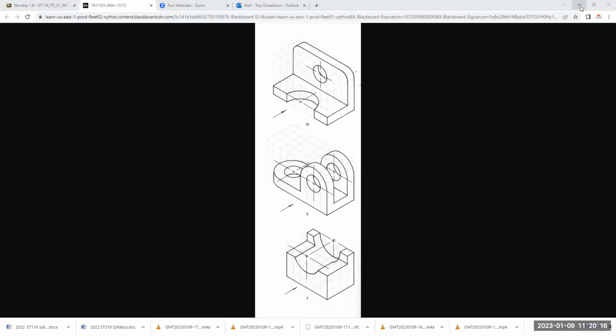I don't do that because this is small. I like big, like lots of space, right? So here's where I draw. But in paper space, this is where the title block should go, general notes, anything like that, not dimensions. Dimensions need to be in model space, tagged to the model.